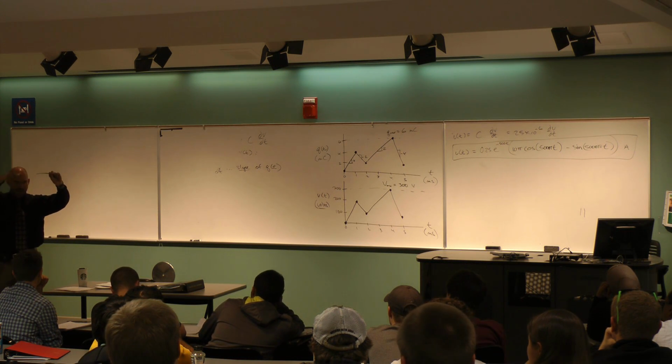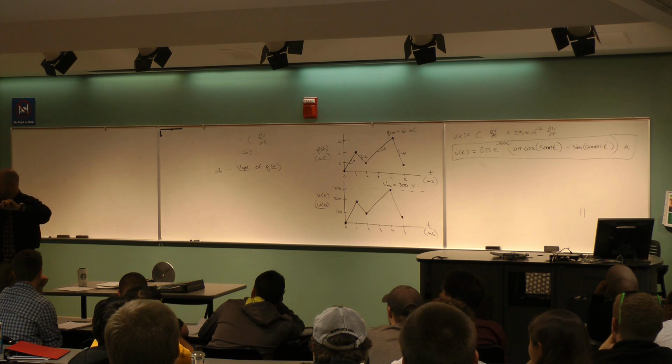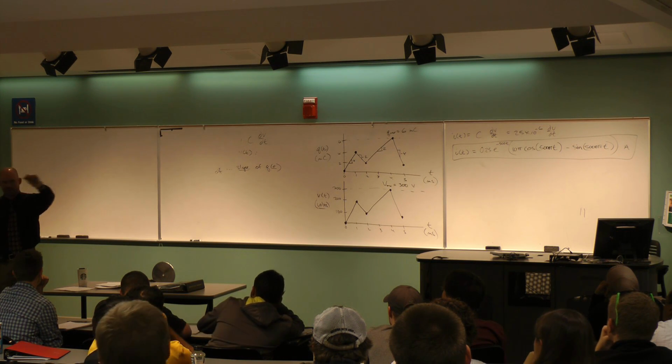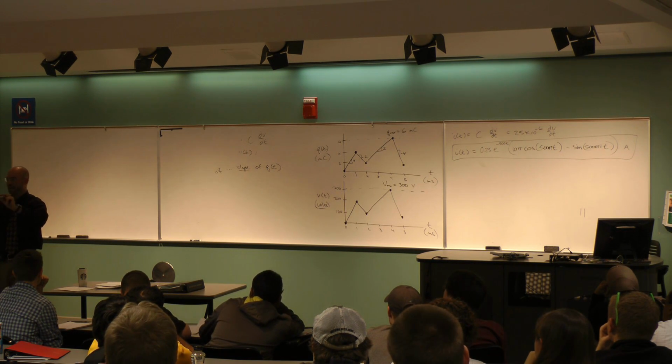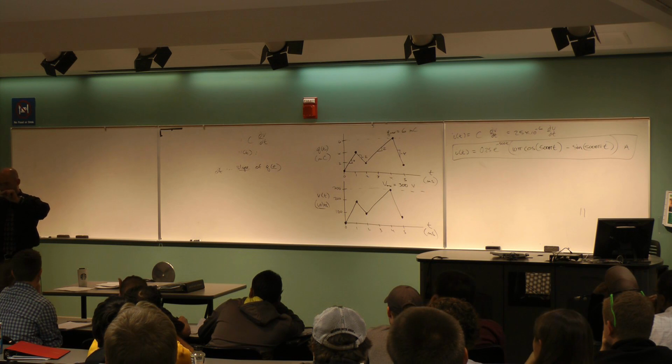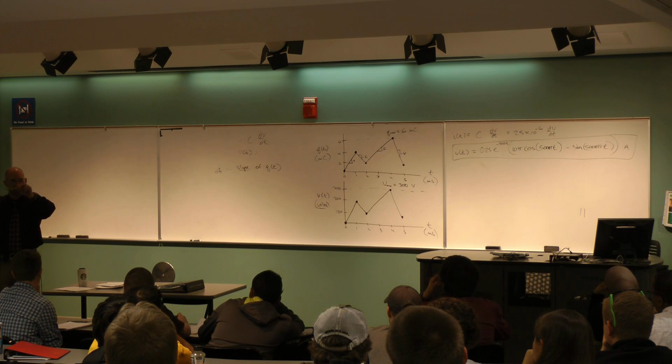And so I can take this beam and bend it, and it'll be curved now, all right? And if I bend this thing enough, I can probably snap it in two. So this whole issue of design is so it doesn't break, but clearly I could bend it, and then when I take the load off, it goes back to normal, right? And that's elastic deformation. So the whole idea of deforming things like beams is to understand how things deform when we design machines that have components that look like beams, artificial limbs, prosthetic devices that have long pieces of metal or carbon fiber or whatever, where we're interested in the deformations and the forces that go on.